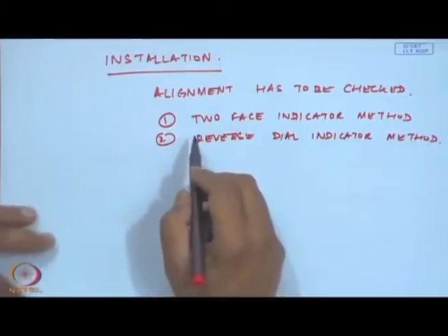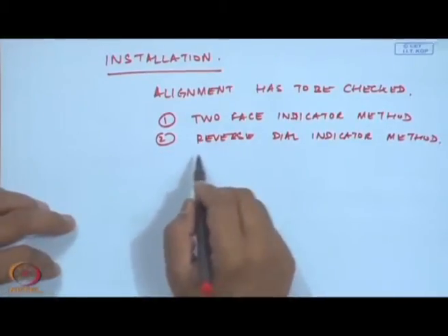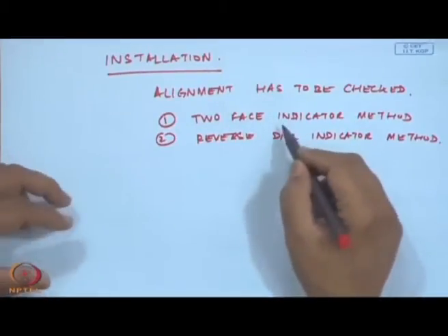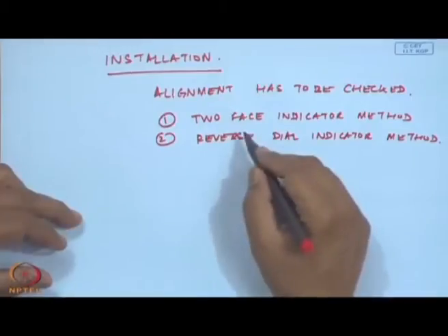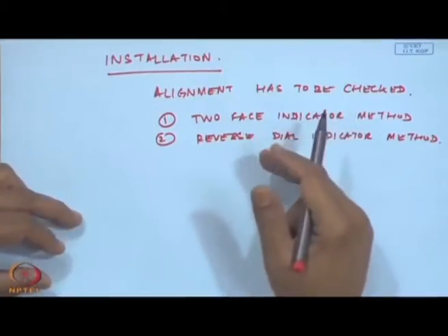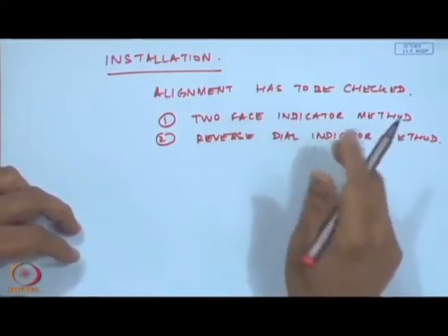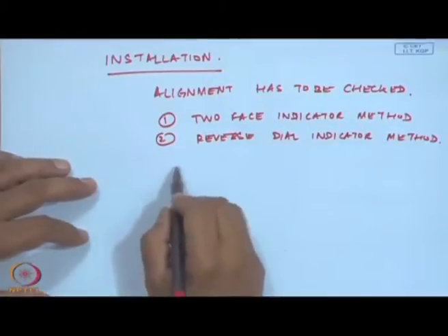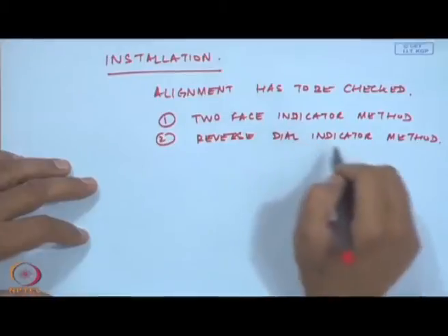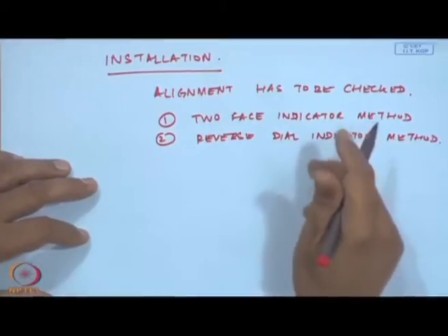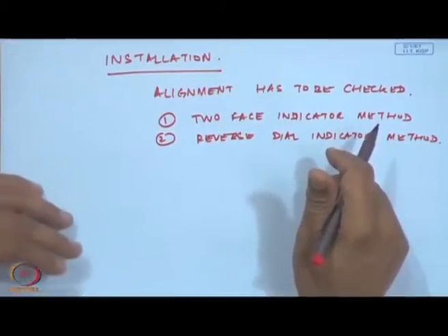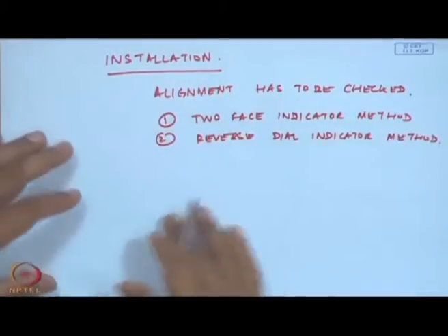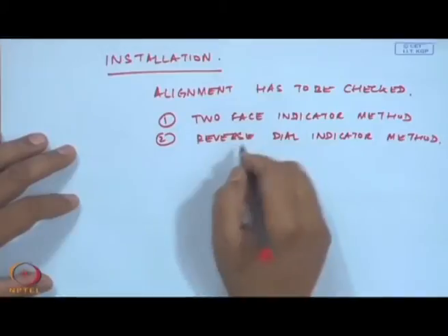Of course, these were the preferred methods in the industry, wherein you measure the radial runouts at 4 different locations, that is the 12 o'clock, 3 o'clock, 6 o'clock, 9 o'clock locations, and then estimate the average radial runout, and then use the shims either in the vertical plane or the horizontal plane or across the 2 foundation axes as I discussed.